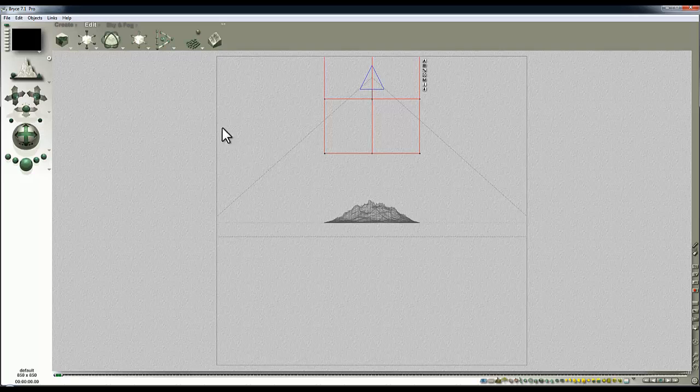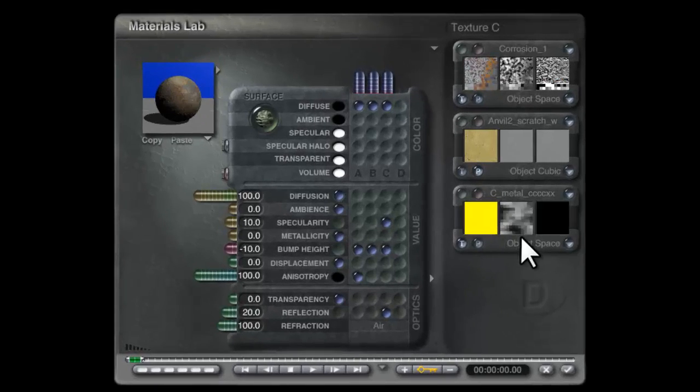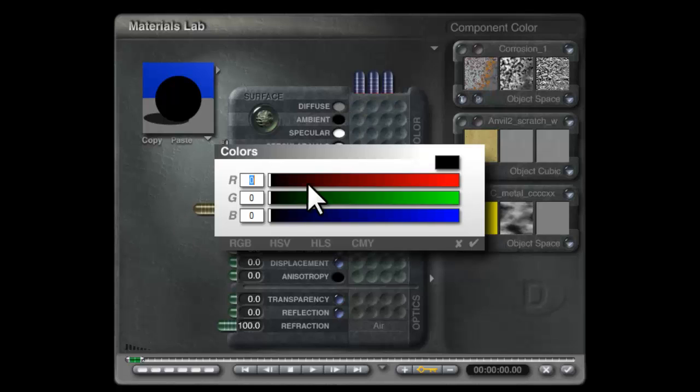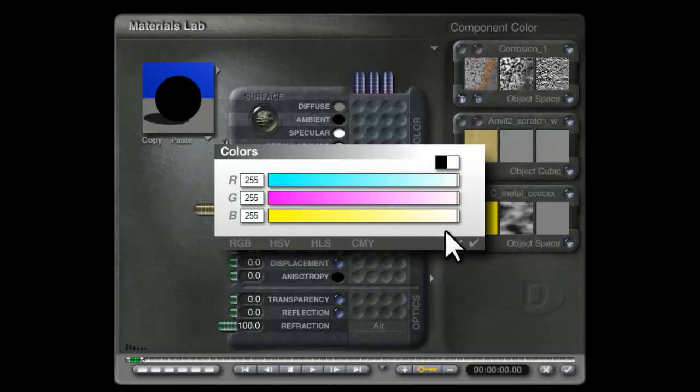Okay, we're not seeing anything yet because I've not set the material up and I've turned all the sun off. So if I go into the terrain here, modify the material, I'm just going to use ambient channels. None of these other channels are necessary, so I'll just set this to 0 and there, and this is my curvature filtering one, and that's going to control ambient. So I'll just pop a blob in ambient there, put these other blobs down, turn ambient response up, get rid of diffuse, and I need that to be fully white.